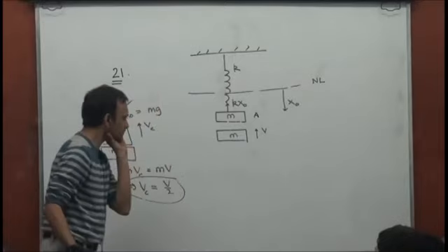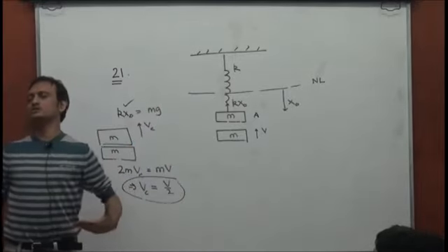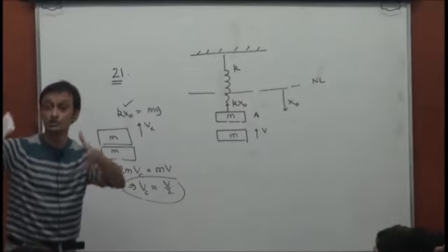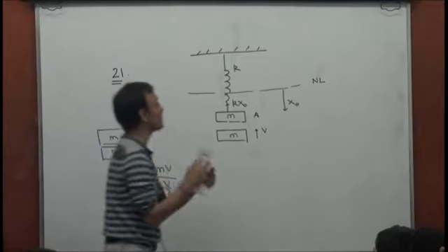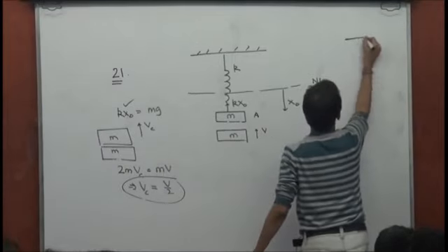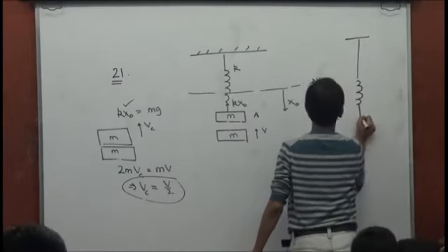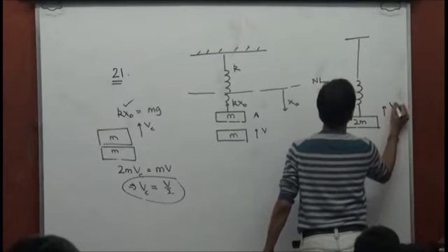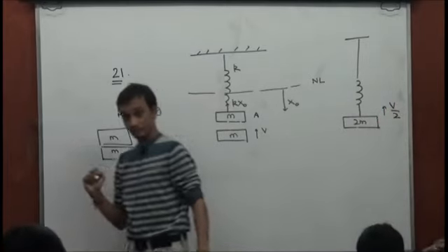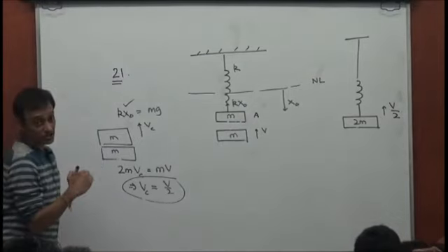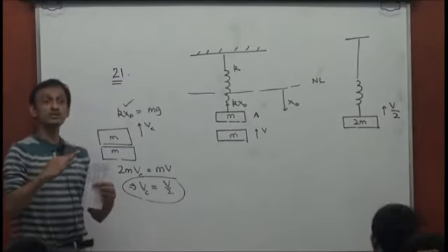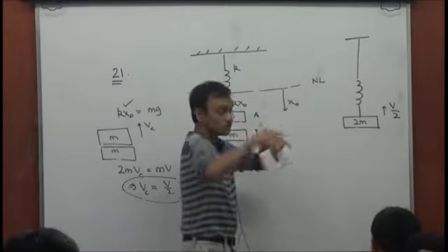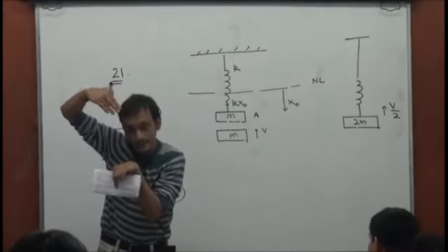Okay. So then, the combined velocity just after collision is v by 2 of now a lumped mass 2m. One single mass 2m with a velocity v by 2 now. That's the scenario. And the spring is not relaxed. The spring is elongated at this juncture by an amount mg by k, right? At this point, the spring already has a built-in elongation, mg by k.